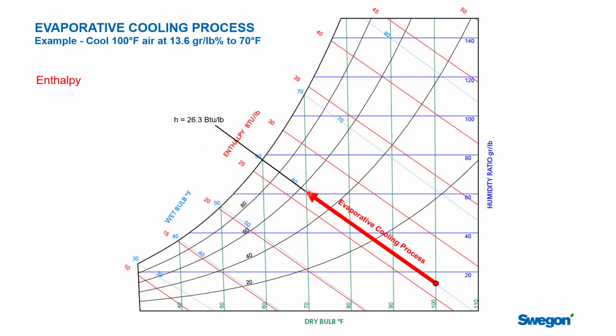So if you're in a desert place where the air is very hot and you have access to water, Phoenix and the Colorado River, you can use that water, expose it to the air, and you'll get adiabatic cooling from that. And it makes a huge difference. The higher humidity is actually a little bit more comfortable, and so this is a very energy efficient way to cool air, as long as you have access to a water source to do that. So that's the evaporative cooling process, and thank you very much.